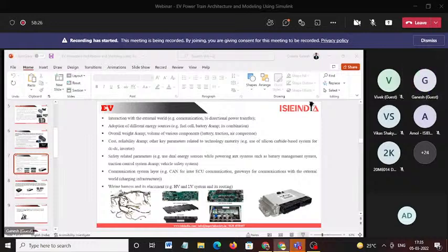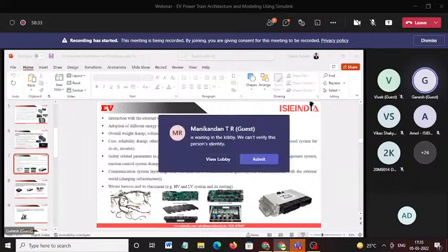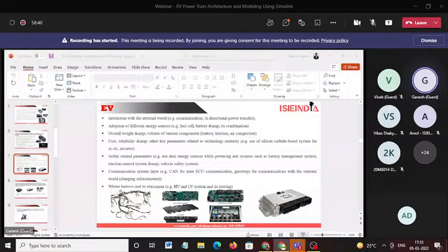When it comes to the IC engine, if your vehicle stops suddenly, we first check whether the fuel is there or not. Sometimes we do a jump start, so the engine starts automatically. But coming to the electric vehicle, many people think the vehicle will stop only if you have less charge. But the VCU is the control system. Sometimes if it does not work, that time also it will create issues during operation. That's why the VCU plays a more important role in the electric vehicle.